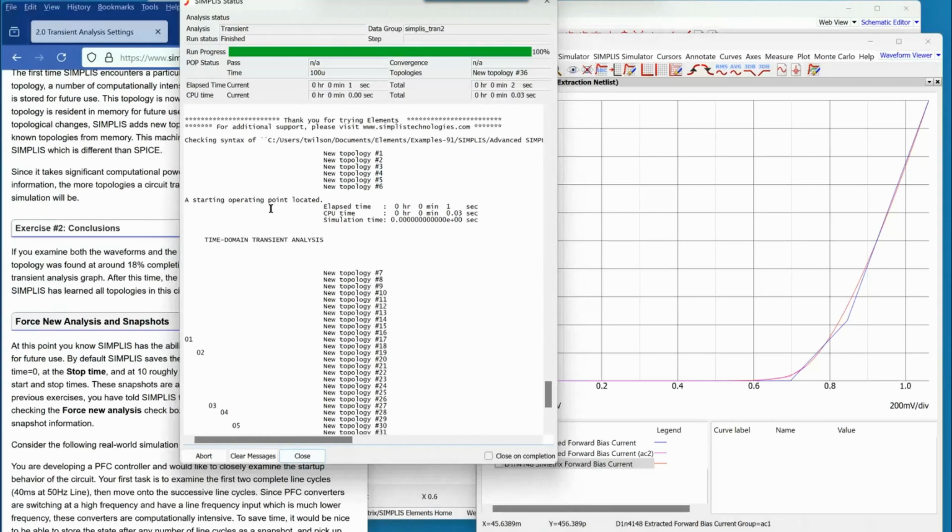it'll say, oh, the oscillator should be high. It solves for that. But then, if the capacitor doesn't have initial conditions, oh no, the output should be low. And then SIMPLIS makes it low and it's, oh no, it should be high. So there's no solution. And like I say, SIMPLIS is very conflict averse. It doesn't like to resolve conflicts. So here it's got a circuit that no matter what state I put it in, it says I should be in a different state. As soon as you give that capacitor initial conditions, then everything's fine. SIMPLIS is just happy as a clam and charges ahead.